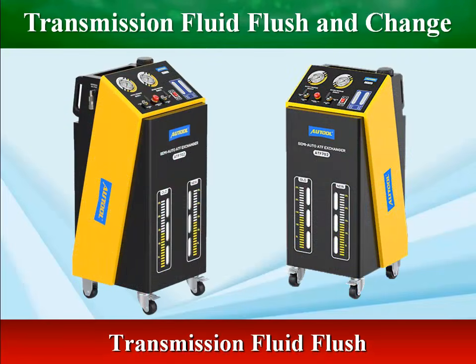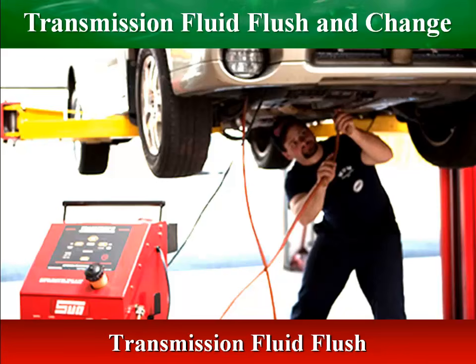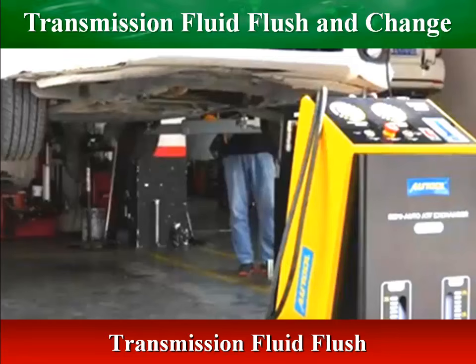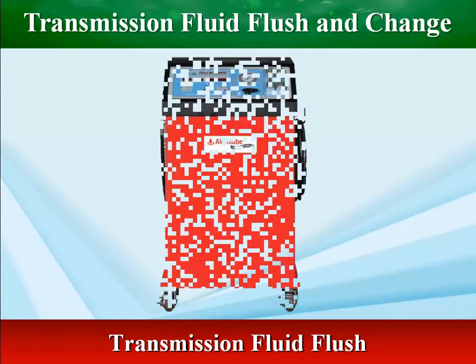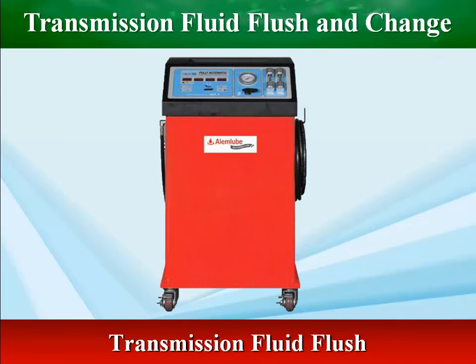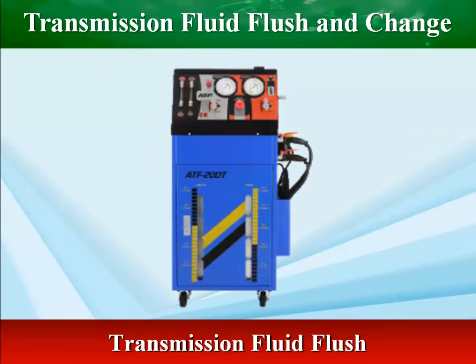A transmission flush requires specific and professional-grade equipment to completely replace the transmission fluid in a vehicle. It's designed to remove old, contaminated fluid and replace it with new fluid, often including a cleaning process. A transmission flush helps maintain transmission efficiency and prevents overheating. Many manufacturers recommend a transmission flush every 30,000 miles or 2 years. Some suggest a flush only every 100,000 miles, and others don't recommend a transmission flush at all.